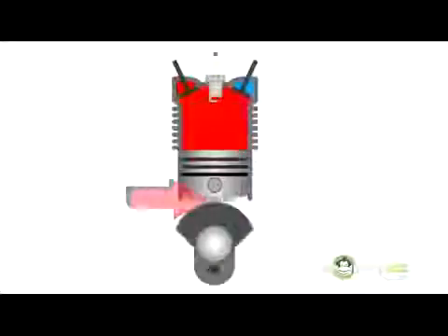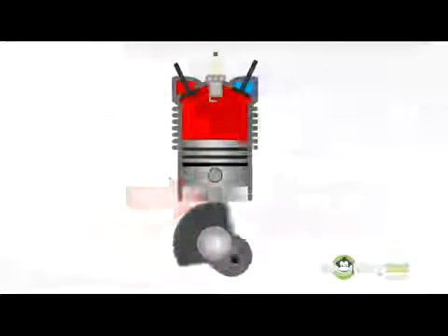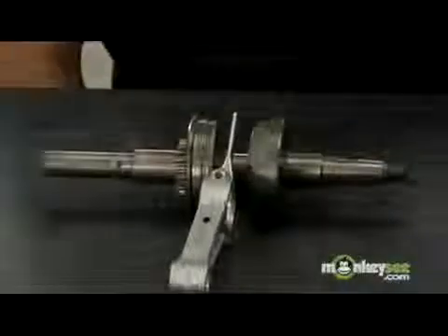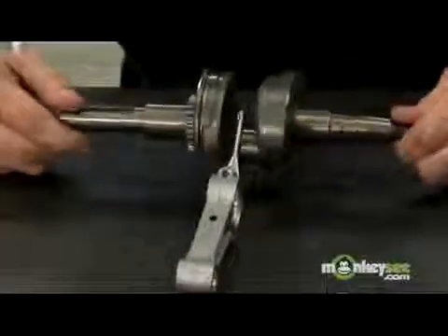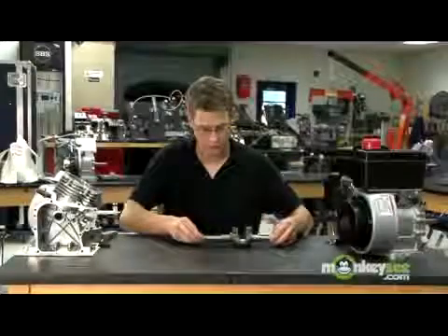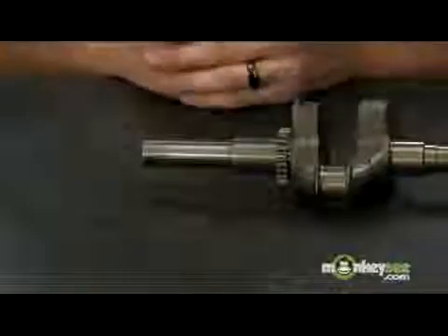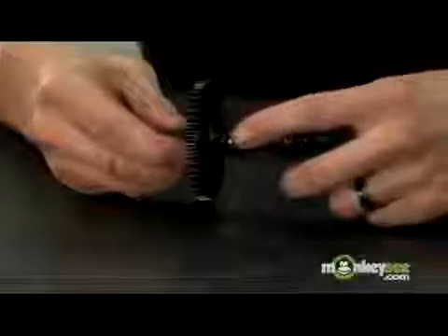The crankshaft is the mechanical linkage between the drive shaft and the piston assembly. The piston is attached to the center of this crankshaft and oscillates up and down as the crankshaft rotates. Another feature of this crankshaft is a gear which links the motion of the crankshaft to the camshaft, which I'll illustrate next. The camshaft is an important component in this engine that has 2 lobed features on it.